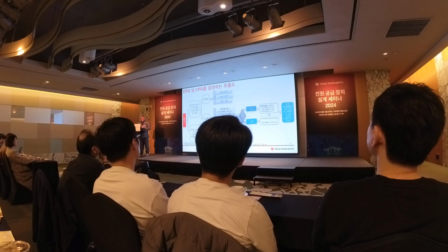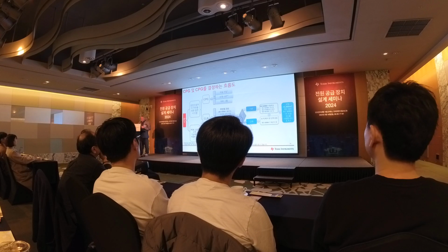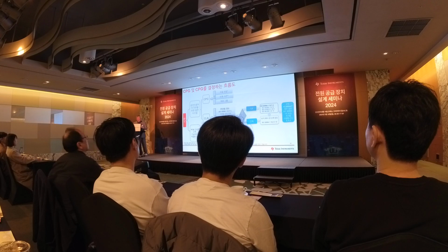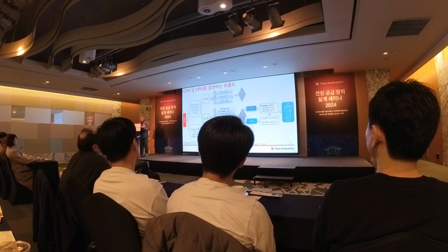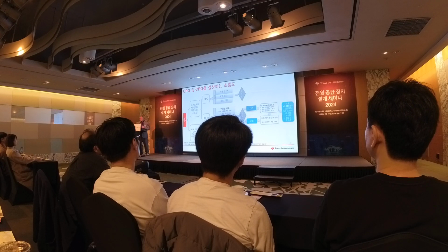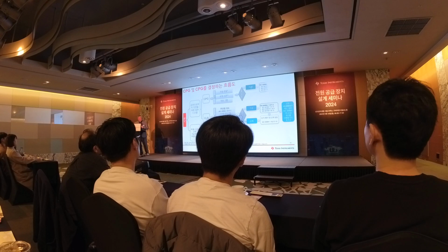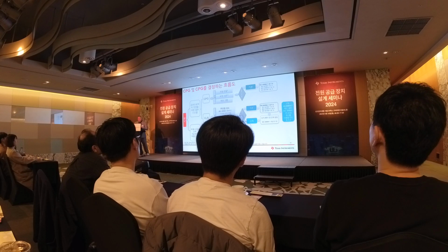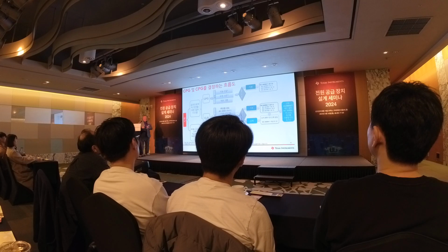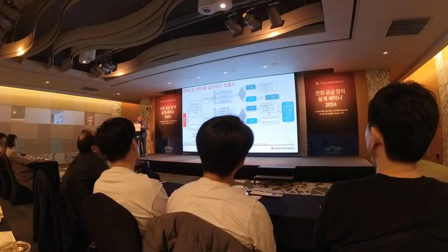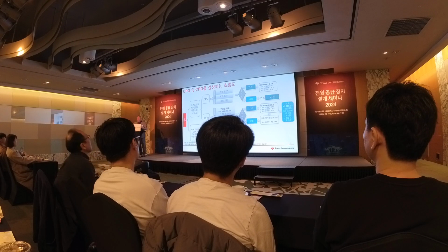Okay, for the creepage, I need to determine three factors. So I need to determine the working voltage, the pollution degree, the material group, and then I do the same set of questions, whether it needs to be basic or reinforced insulation. If it's basic, then I refer to IEC 60664, table F4. If it's reinforced, I do the same thing as before, 2 times basic insulation.